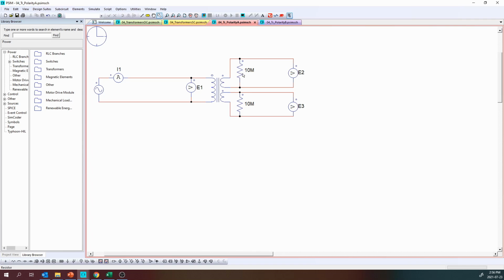Again, these two resistors here are biasing. So they are very large. So they're basically no load for this transformer. They are not going to affect the behavior of the machine by having these two super huge load resistors, which are very, very small loads. And so that's something that's sometimes confusing. But keep in mind, the bigger the resistor, the smaller the load, because the less current it can flow through it.